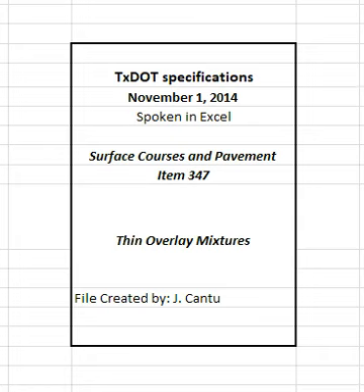Use fine aggregate from coarse aggregate sources that meet the requirements shown in Table 1 unless otherwise approved. Test the stockpile if 10% or more of the stockpile is retained on the number 4 sieve and verify that it meets the requirements shown in Table 1 for crushed face count, TEX 460A, and flat and elongated particles, TEX 280F. Table 1. Aggregate quality requirements.